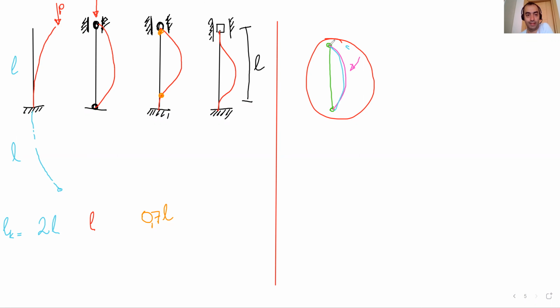So let's find the two hinged members shape. Total curve, where it is. It's here. It's in this portion. In the previous example, it was like this. So when we take a look at this shape, we need this length for buckling length. This is less than the previous one. It should be 0.5 L. Okay.